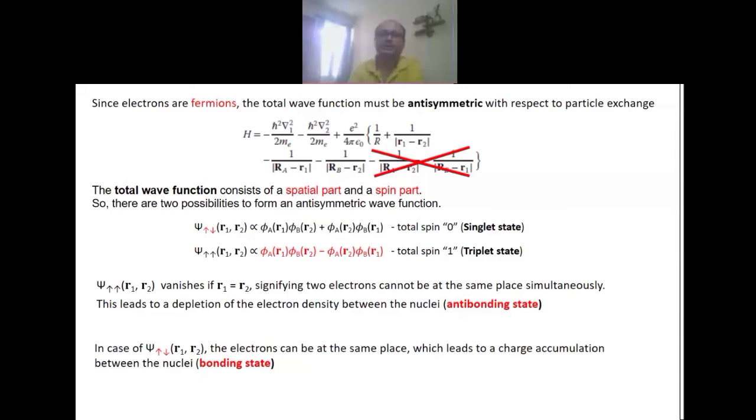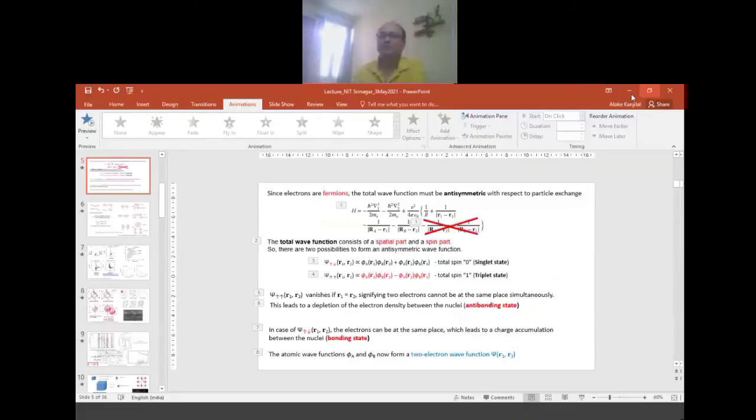Here you can see that in silicon nanocrystals, whenever we bombard this silicon oxide matrix, we get the silicon nanocrystals. Utilizing this, we can also pump the erbium ions, and these erbium ions emit at 1.54 micrometer, which is the telecommunication wavelength. We showed that without utilizing any costly laser, we can easily pump the erbium signal, and we can explain this by the energy transfer process.